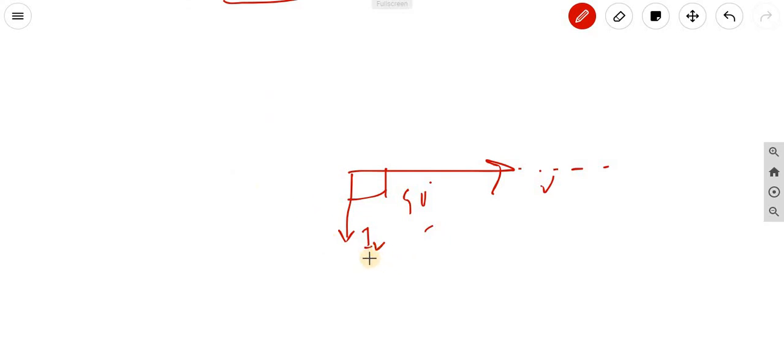So as you know, for an inductor the current is lagging by 90 degrees. The voltage across the inductor is V, and the current through the inductor is IL, and the current through the capacitor leads by 90 degrees. So see here, IL and IC are opposing each other. If there is any condition where IC and IL oppose each other equally, then the resultant current would be zero.